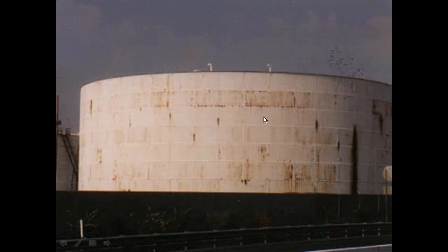The specification is going to usually tell you where to test, but sometimes it doesn't. When it doesn't, if you want to stop a failure, watch the test at the areas of corrosion, at the areas of coating failure, and at the weld seams.